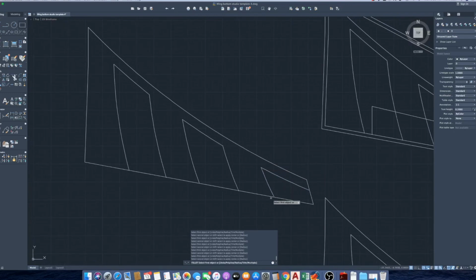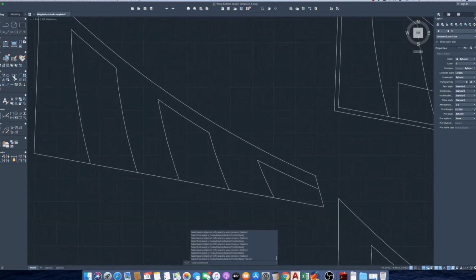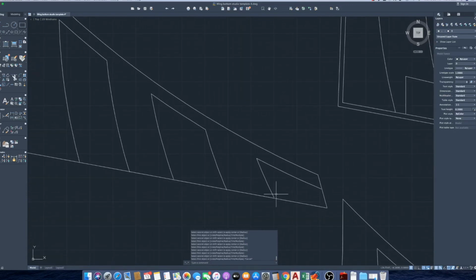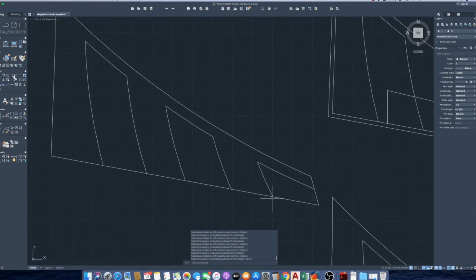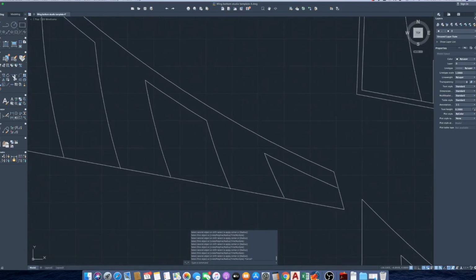So you can't do these because you'll lose this entire line. If I want to fillet it from here to here, or from here to here, it doesn't work. If I do this fillet command from here to here, you'll notice I lose that whole line. So I lose this piece that I want to keep, right? So for these, I'm just going to do trim.